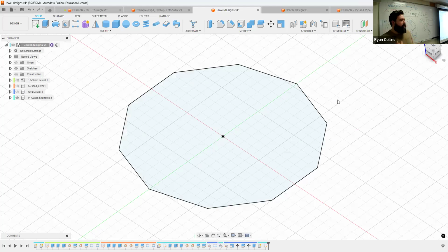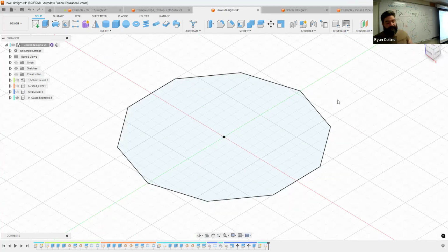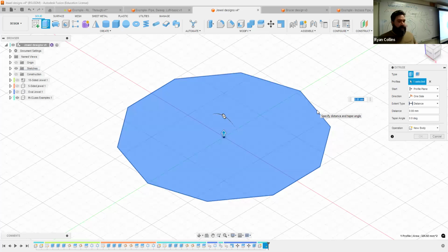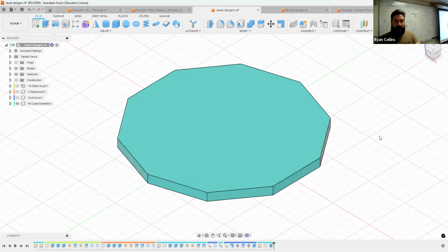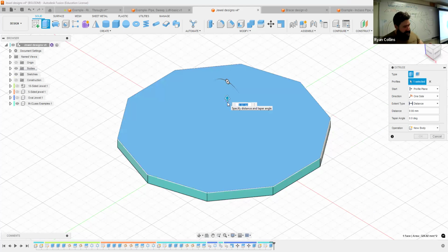From here, we're going to do 3 different extrusions. We're going to hit extrude. The first one, we'll do like 1 millimeter. Or even half, something like that. That's fine. We'll say 1. Keep it whole numbers. All right. Repeat. Right-click to repeat. Selecting the top, not the sketch, the top that you just created, the plane you just created. I don't know, let's go up to like 5.